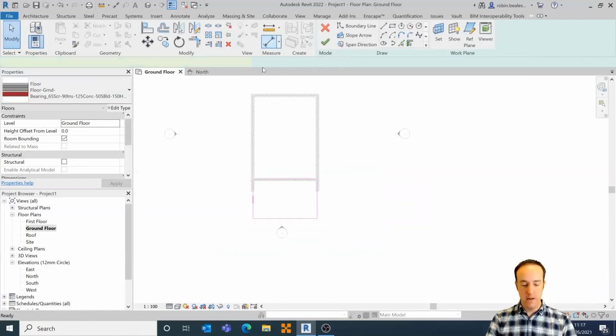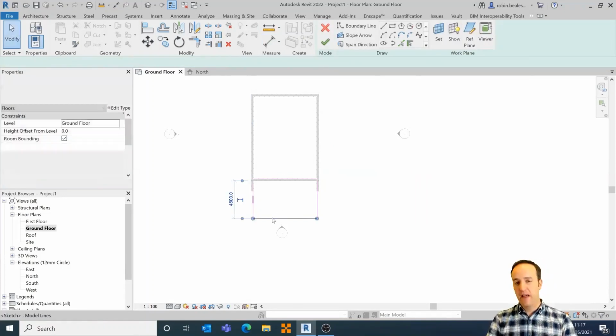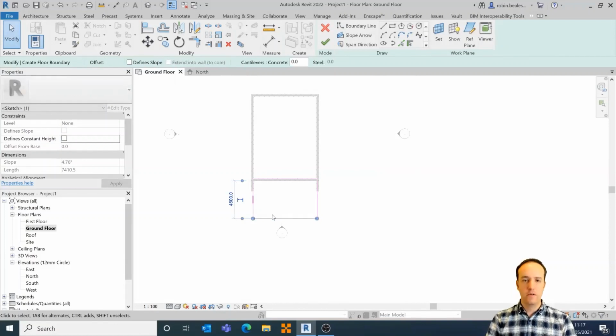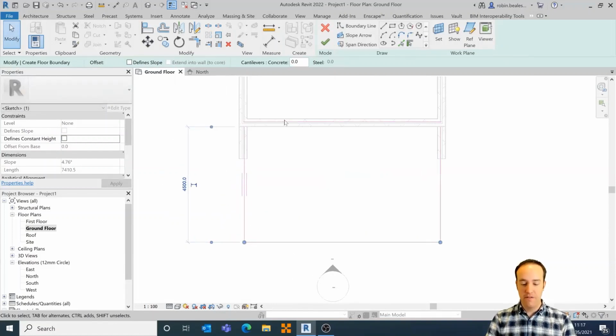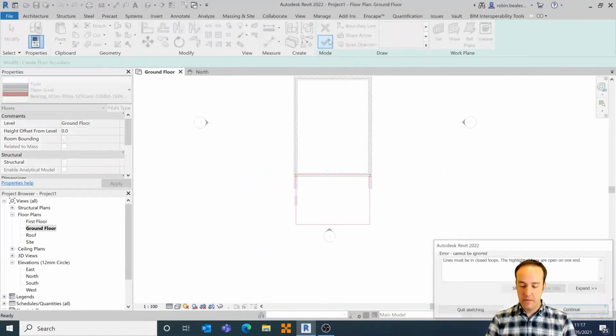Absolutely, we can place a permanent dimension at any point just by selecting 2 edges, 2 faces, or 2 points. But typically, until you tell Revit that you want those dimensions on, they're hidden. We select what we want to move, and if I want this to be a 5-meter seating area, I select the object I want to move, and then I can just make a quick change to that dimension easily. Let's press the tick to place that down.